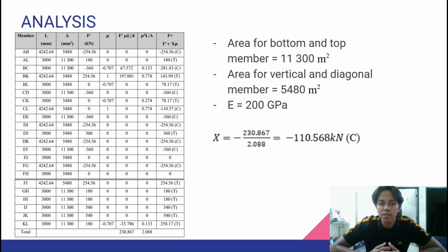So after we calculate the force of each member for F prime and mu, we create a table to calculate X. Actually, X is the real value of the force of the redundant member.